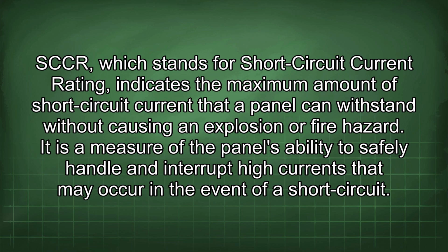SCCR, which stands for short circuit current rating, indicates the maximum amount of short circuit current that a panel can withstand without causing an explosion or fire hazard. It is a measure of the panel's ability to safely handle and to interrupt high currents that may occur in the event of a short circuit.